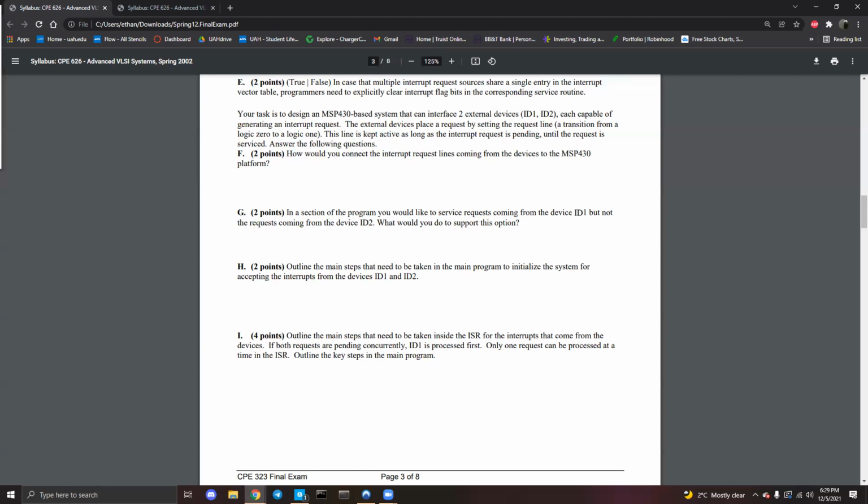You'd also set which change on the pins corresponds to an interrupt, which means setting it to rising edge. So it's three steps: set the pins to input direction, set the pins to interrupt enable, and make sure the interrupts they are receiving are based on a rising edge transition. And then you have to enable global interrupts. He doesn't add that one, I think because it's kind of just assumed.